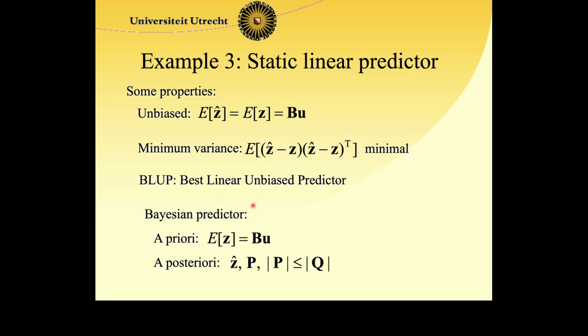We also call it Bayesian. That's the same as the Kalman filter. They actually all make use of Bayes' rule. So you have some a priori estimate, and then with the probability of the measurement given a certain state, we can also calculate the optimal prediction given the measurements.